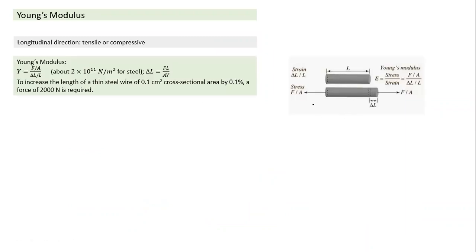And this is the part we have done in my last class, Young's modulus. I'll just skip through this part we have done. What we understand here: change in length when we apply a force is equal to FL by AY, so the change in length is proportional to force. And when we apply a force like this, the material is applying a resisting force in the opposite sense. Very similar to a spring. So when the rod gets elongated, the change in dimension is towards right, and the force applied by the material is towards left.